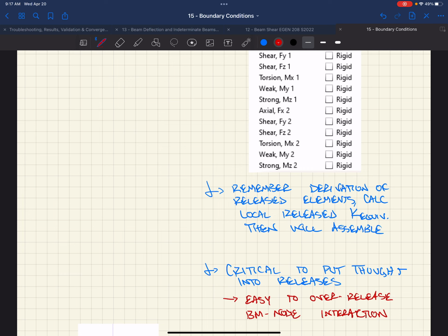because in VA we're putting nodes and looking at center line to center line. We're going to have a node at the beam to column intersection. And when we're looking at that, we can't just stop here, right? So we have this beam and this column framing in. What do they end up doing? Well, they put this huge cheek plate assembly that goes across all of this. They bolt it all up, or weld it all up. So this whole system now becomes super strong.